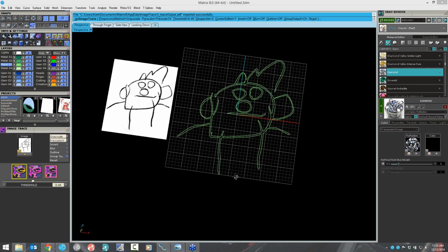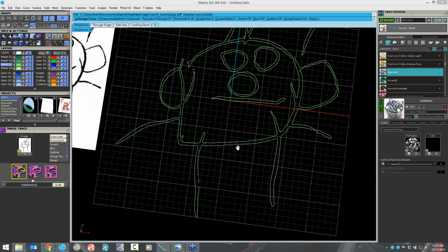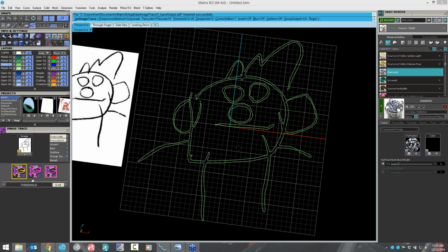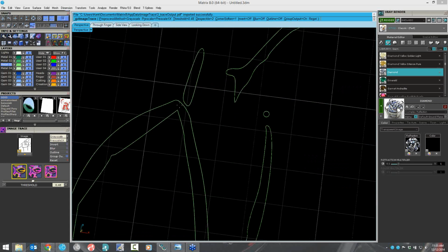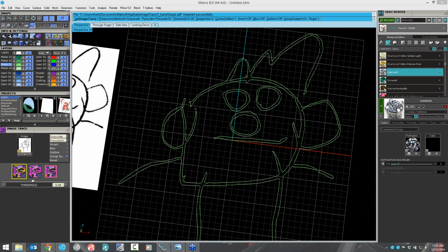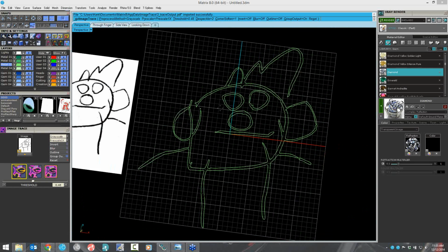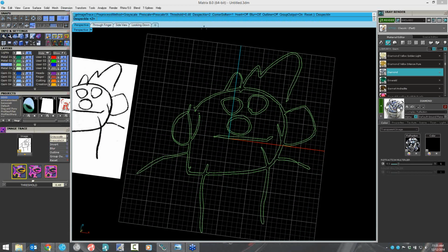Now, it does a great job, image trace does. You won't find any overlapping curves, anything that flips around and goes back over itself. That won't be in there. You can see we have a couple little dots here. Those we call speckles. And you can certainly come in here, and I'm going to increase the speckle to 4, and it'll get rid of those speckles. We can smooth out the lines by blurring the original artwork. We can do all sorts of stuff.